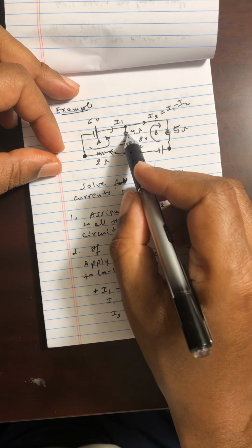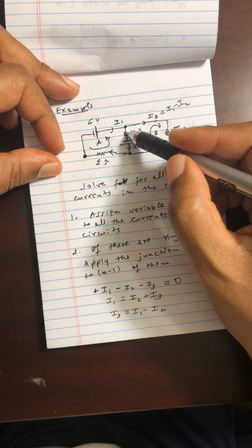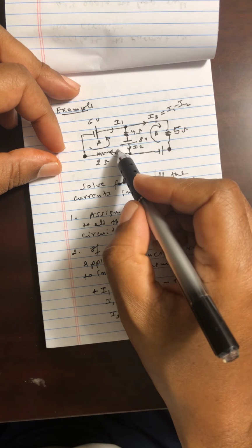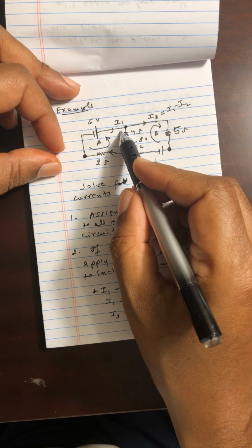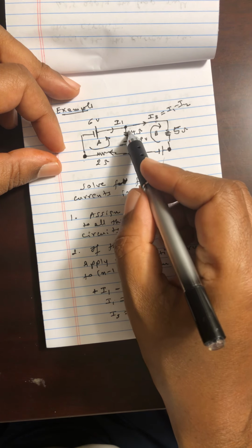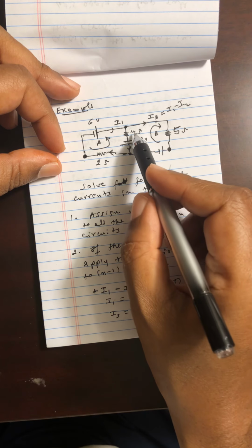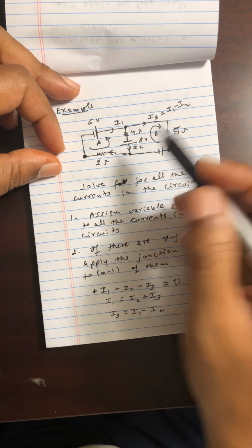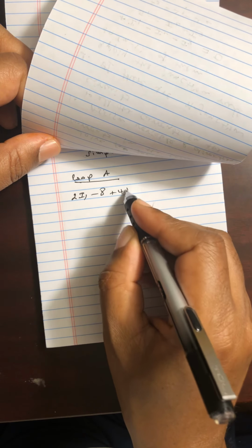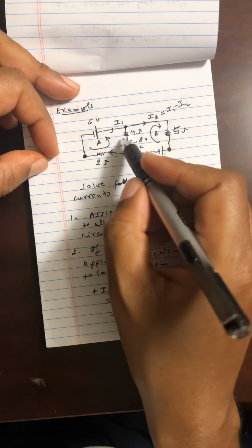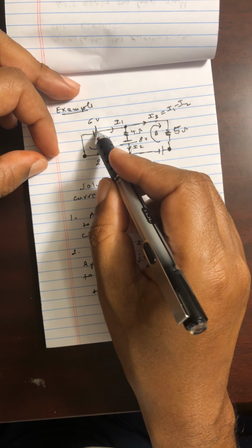We have this resistor over here. Now look, the current is going this way, but I'm traversing it opposite to the direction of the current. So the potential difference across this resistor is going to be taken to be positive, okay? So 4 times the current I2 is going to be positive, okay? So you've got plus 4I2,